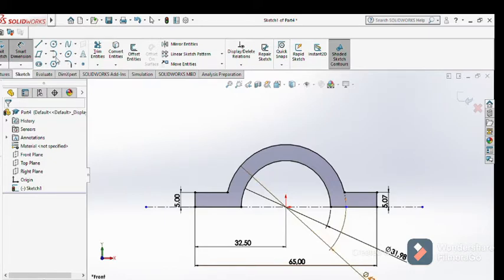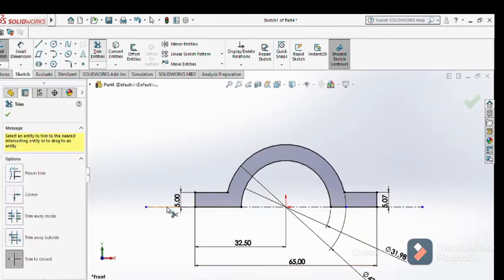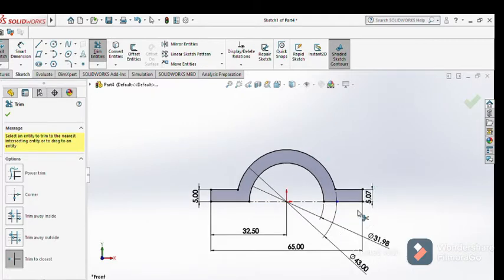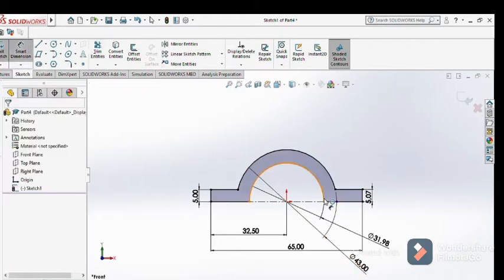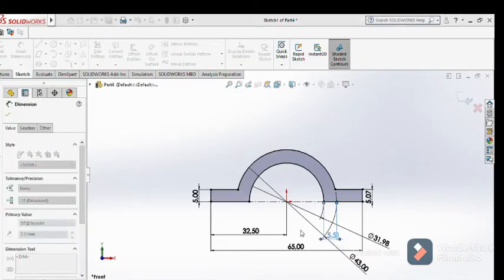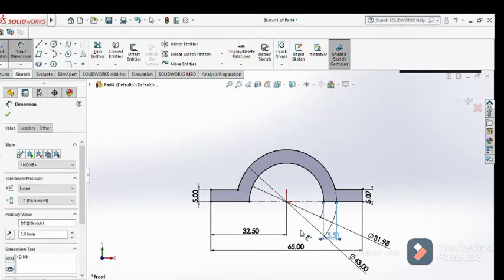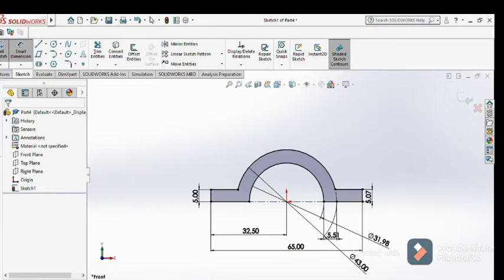In that case, I'm going to remove my center lines from this side, and this side I'm going to be left with the ones inside here. Since there's a measurement that I didn't include, I have to include it, which I usually think is this one. Since it's blue, I'm just going to put it there, and it's just going to be like that. So my diagram is fully defined now. Not yet done. We still need to extrude the diagram.